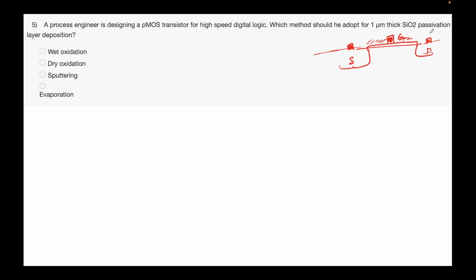Passivate essentially, at the surface there are dangling bonds, because it's a crystal that we are growing and all of a sudden it ends abruptly. So those valencies are not satisfied. What we do is deposit some material, some dielectric like SiO2, silicon dioxide, or silicon nitride, to passivate the valencies of those dangling bonds. That's essentially what passivation means, because they can sometimes have a detrimental effect on your device, especially the breakdown characteristics.